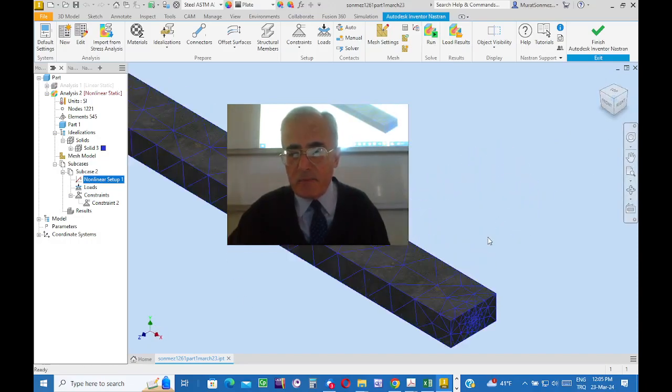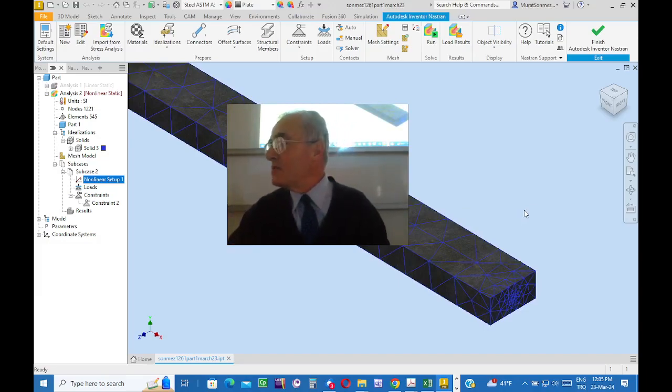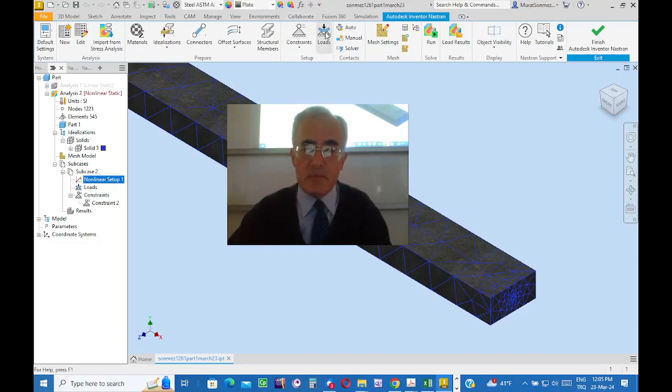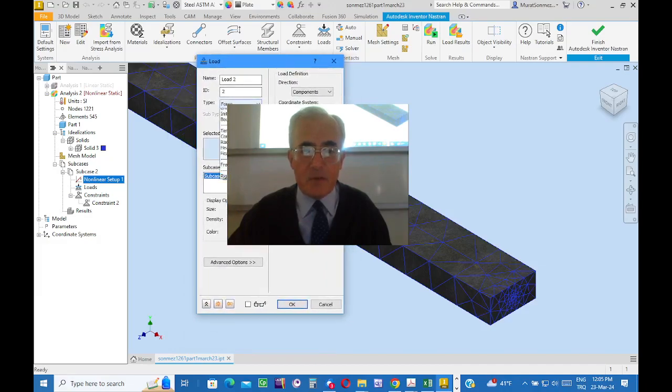Okay, this part of the body we have a laterally directed load. We said that the magnitude is 9,000 newtons. It's a force type load. Click on this, and in the dialog box, drop the list, whether it is moment, hydrostatic pressure, or thermal boundary condition, temperature, radiation, convection coefficient.